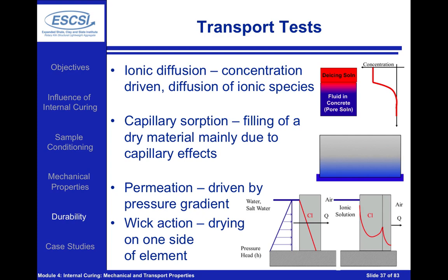Permeation is the next one, where we're driving water in by a pressure gradient, and wicking is where we're essentially having a combination of diffusion and absorption and then a drying out on the other side of our concrete. By the drying effect, we're evaporating water off of our concrete, but we're leaving salts or ionic species behind, and they can actually create a higher concentration right behind that drying front inside of the system.